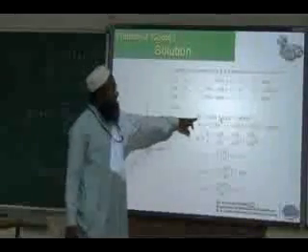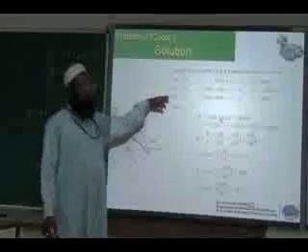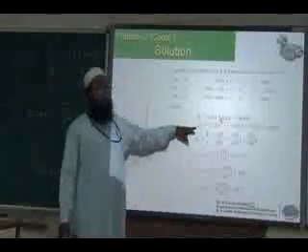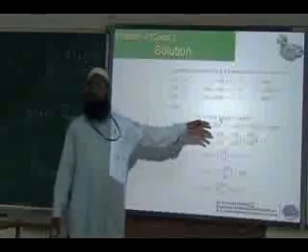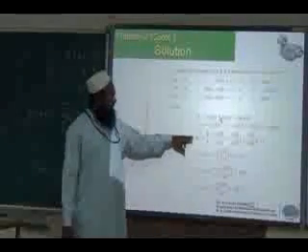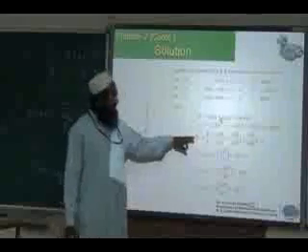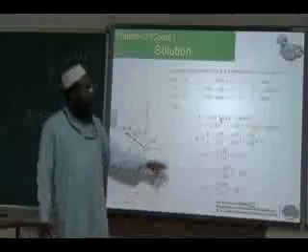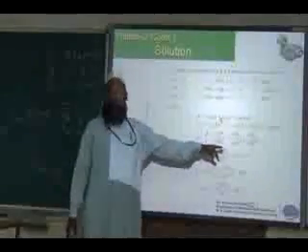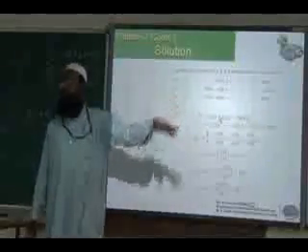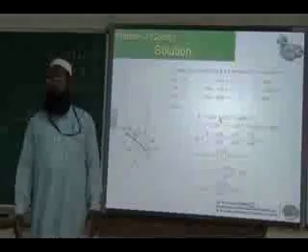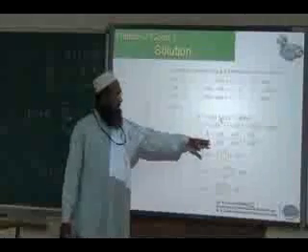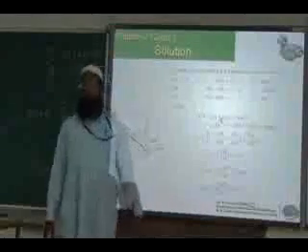After finding Fx, Fy, Fz, we will write it in Cartesian form and its magnitude can be found from Fx square plus Fy square plus Fz square. Then find the unit vector and use the unit vector concept to get alpha, beta, gamma, because the unit vector represents cos alpha I plus cos beta J plus cos gamma K. If you remember the unit vector portions which we dealt with in the last class, this unit vector can be used to obtain the direction cosines.